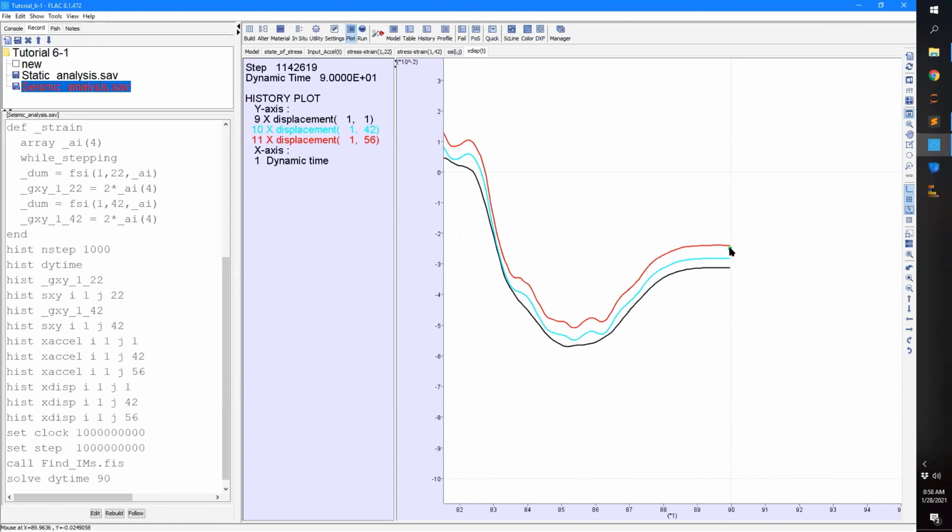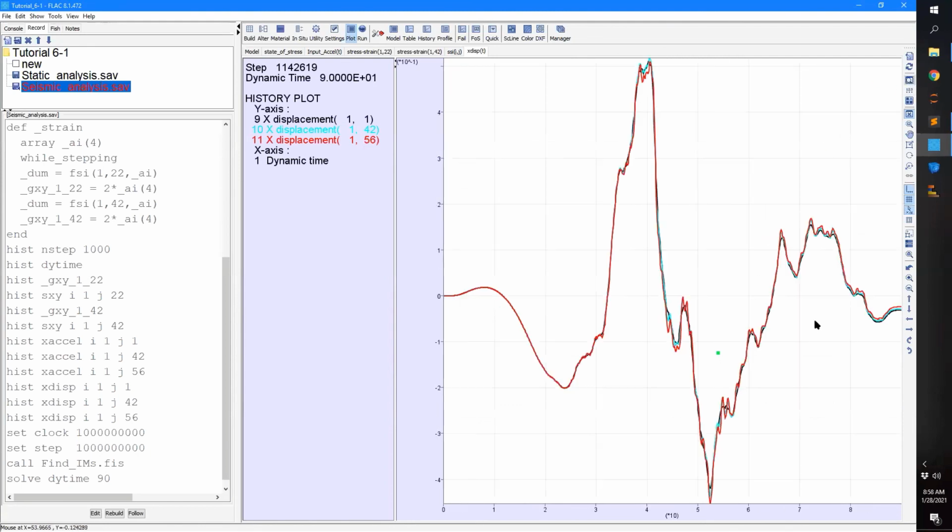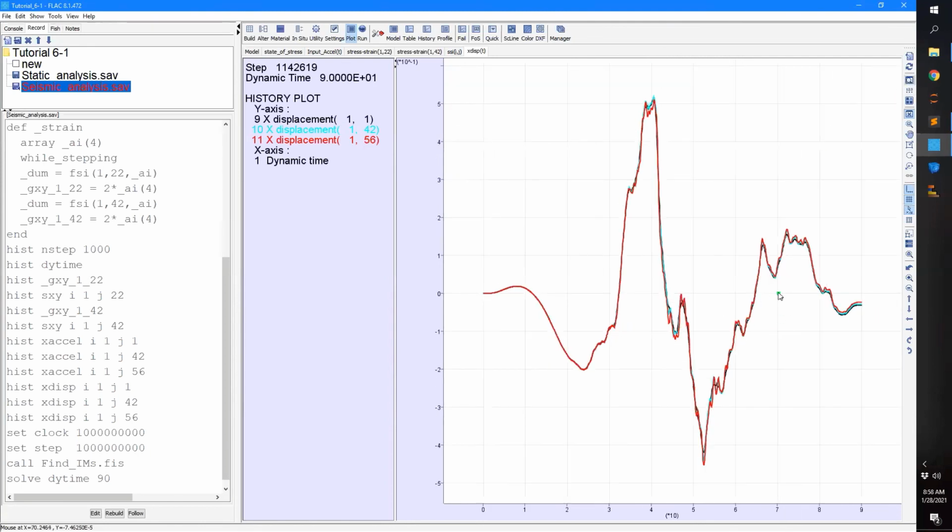So what I always like to do, especially in terms of displacements, is that I always will compute the displacements relative to the base of my analysis. This is also something, well, maybe the ground motion was baseline corrected, but there are sometimes some natural shifts in that. We could also compare, so that's displacement.